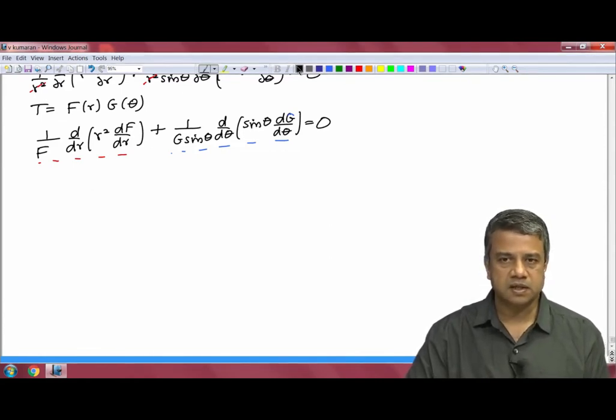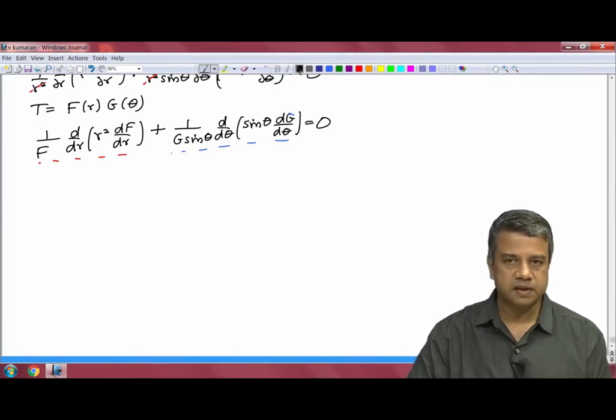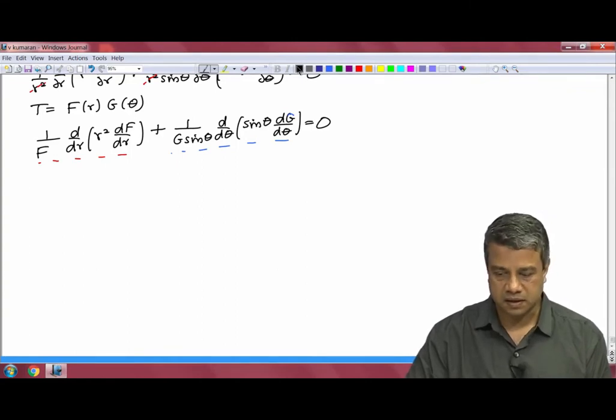Note that the inhomogeneous boundary condition is in the r direction as r goes to infinity. That is where you have applied a temperature gradient, and that is what is driving the temperature variations in the vicinity of the particle. So, you would expect homogeneous boundary conditions in the theta direction, but it is not obvious here because we do not have a boundary in the theta direction.